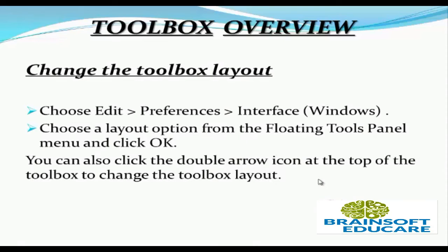Change the toolbox layout. Choose the Edit menu, then select Preferences, then click on Interface. Choose a layout option from the Floating Tool Panel menu and click OK. You can also click the double arrow icon at the top of the toolbox to change the toolbox layout.